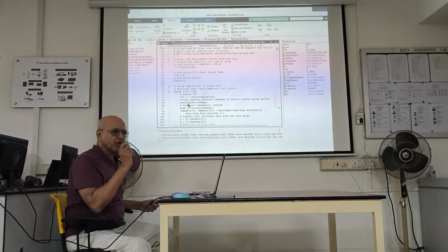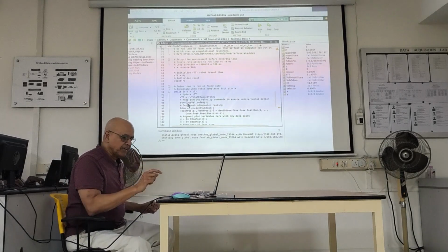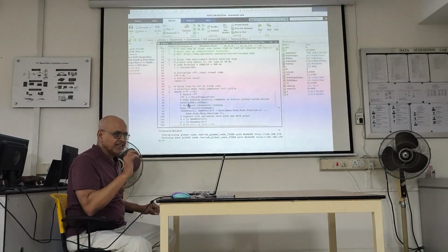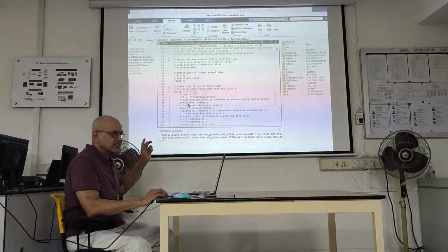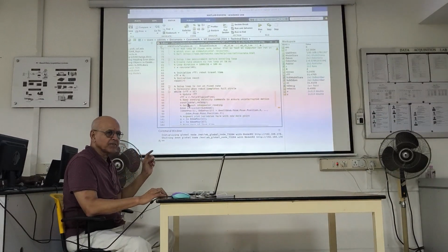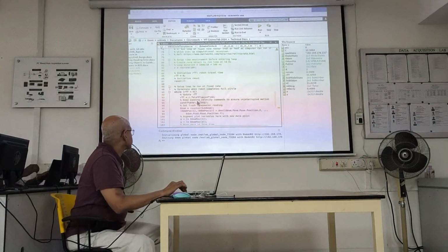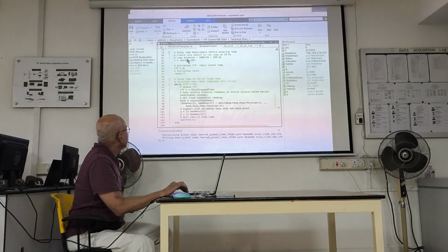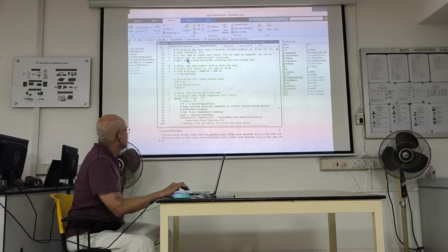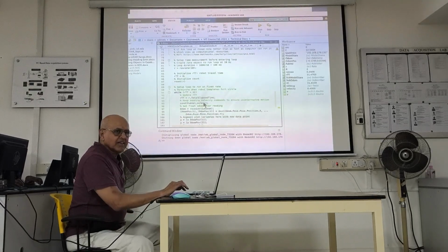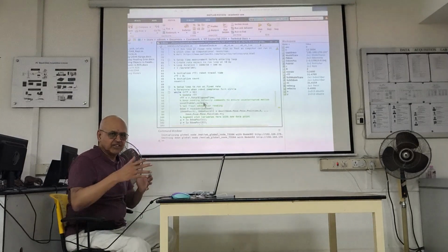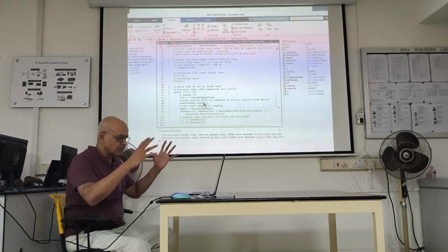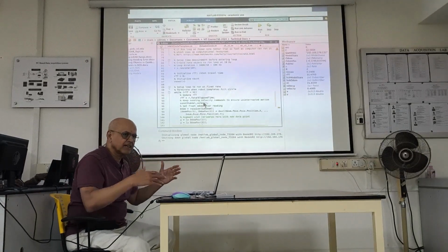And then I told you, you have to keep on telling, even if the velocity has not changed, typically you have to tell the robot drive, drive, drive, drive, because it's supposed to be a safety feature that if it stops receiving those commands, it will stop. That has not been programmed at all in Turtlebot 3, but you'll find it on many other commercial robots. Then you publish it, because you've already packed the velocities up here somewhere, and so you can publish it. In your task, if you want to change the velocity, you change the velocity and then publish it, right? So the logic is now emerging. Because if you want to drive the robot like this, then you have to change the velocity.